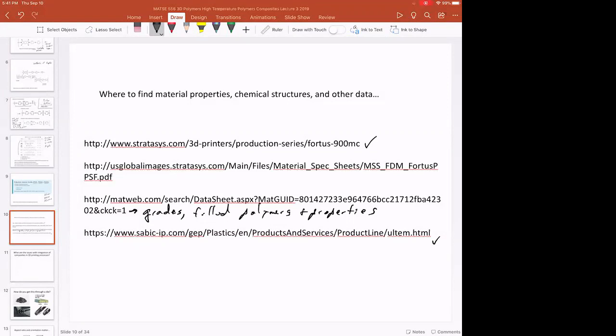All right, so like I said, we're going to start talking about composites. And composites, the way we're going to approach composites is basically polymers filled with something that's not a polymer. So there's lots of different ways to make composites. Fiberglass is a composite, even a laminated structure where you might glue rubber insulation to a metal panel. That's a type of architectural composite. Of course, concrete is a composite material because it's got aggregate and cement in it. But we're going to talk about composites primarily from the angle of a polymer with other stuff in it.